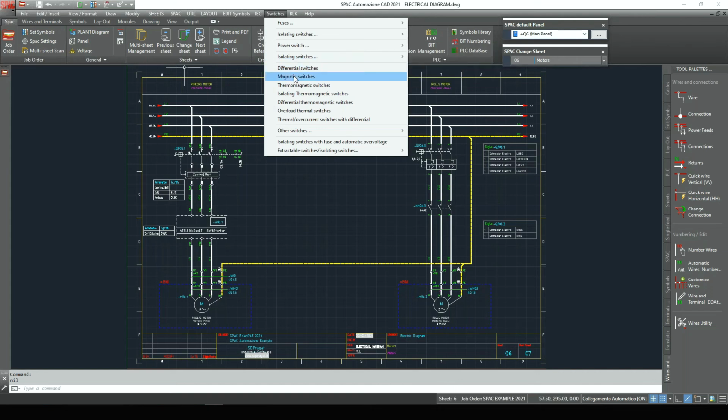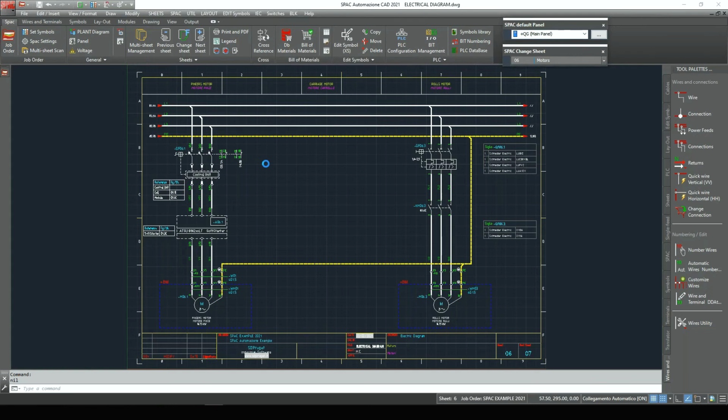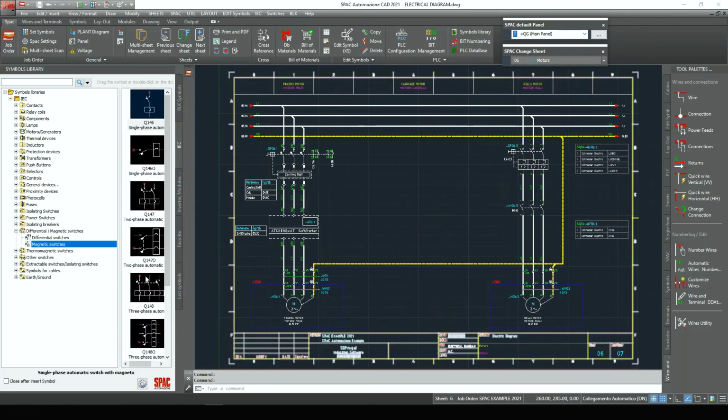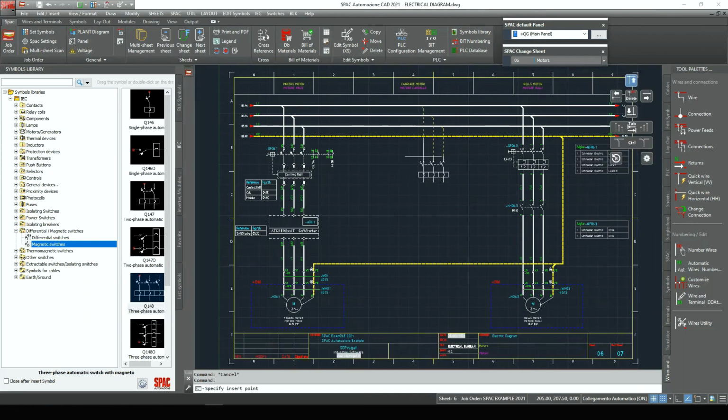You can select the type of component you want to insert, select it from the left window that will also show a preview of the symbol itself, and then using drag and drop, place it in the desired location of the schematic. If you notice, you can see the connection lines that are already placed by the software, so it eases the design of the electrical schematic.